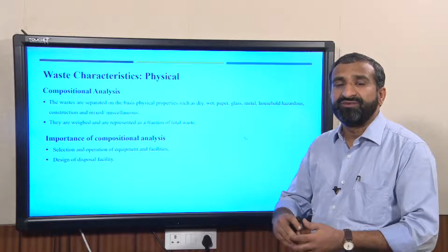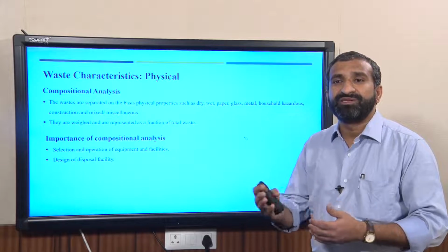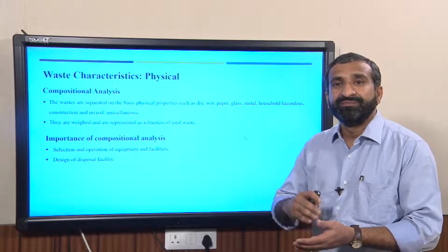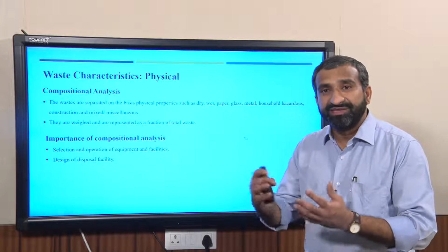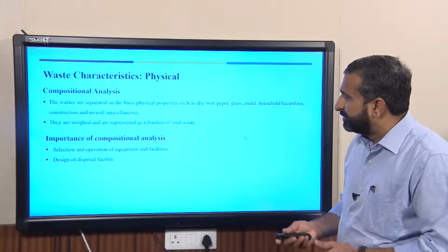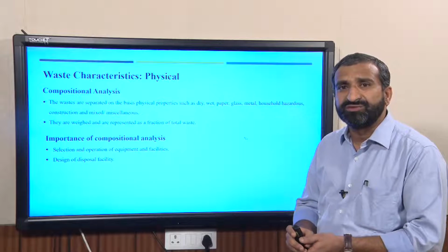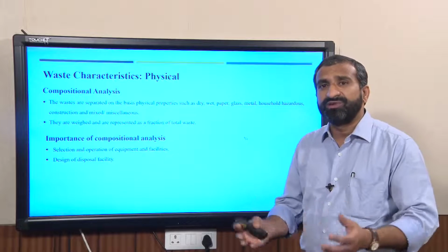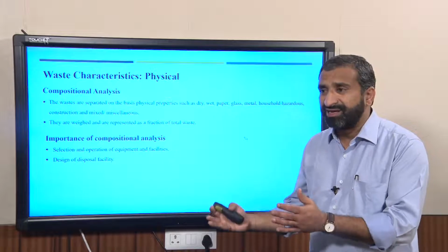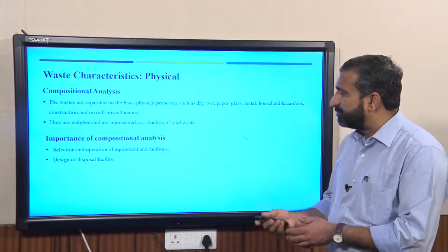And if you are planning an incineration facility and do not know how much combustible matter is present, mainly combustible matter like paper, plastic and rubber quantity, which are very important combustible materials required for incineration. So not only for the treatment process but also for the disposal facility, we need to know how much leachate is produced, or what kind of waste is coming to the disposal site. Based on that we can design the disposal facility.